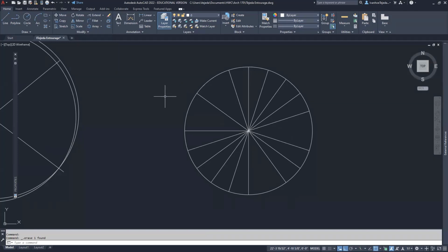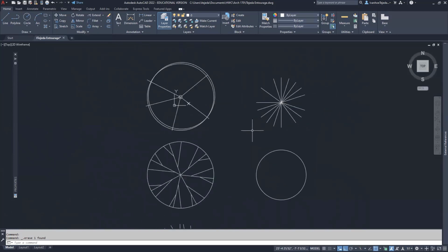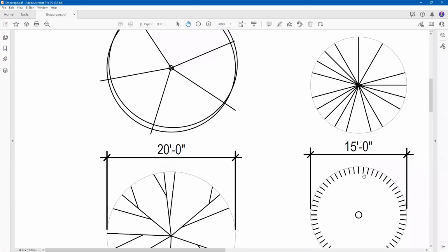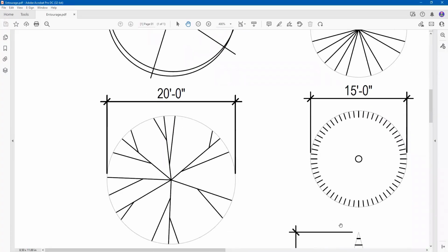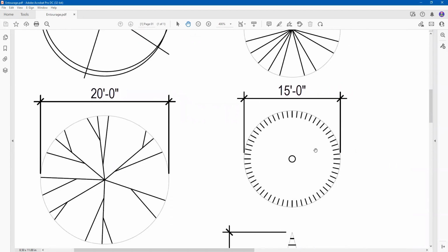And I'll say this too, if you'd like to leave the circle there, go right ahead. If you'd like to remove the circle, you can just click on it and then delete. I leave it in your hands, whatever you'd like to do is fine. And now when I zoom out, you'll see it's meant to represent that tree. The next thing I'd like to do is construct this tree. And I also want to repeat the polar array, only this time I'll keep it associative.